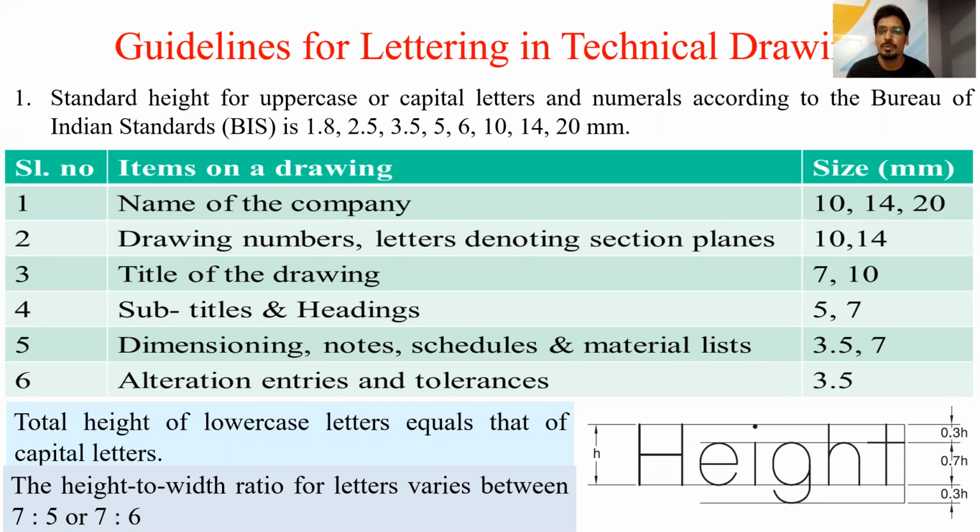It is not possible to achieve exactly 30 mm because there is some restriction due to the human being and due to the machinery on which the object is to be manufactured. So we have to provide some tolerance, and that tolerance should be written in the height of 3.5 mm size.